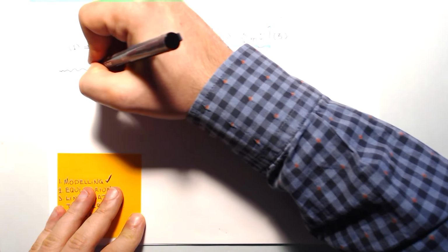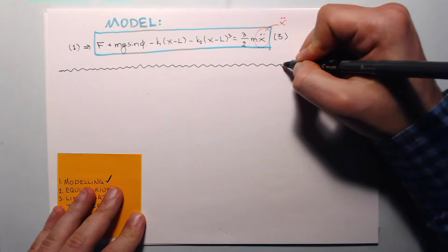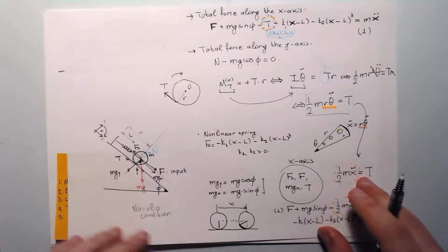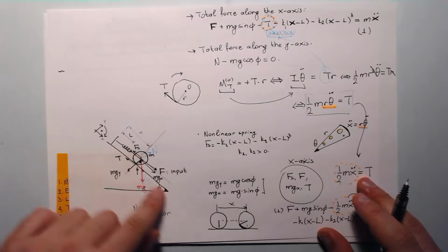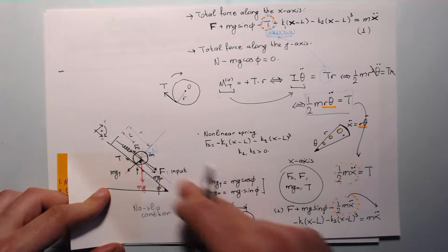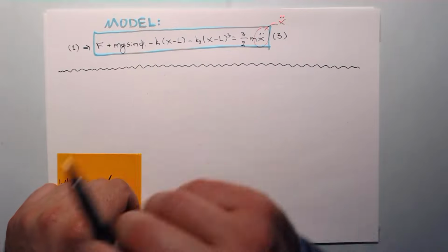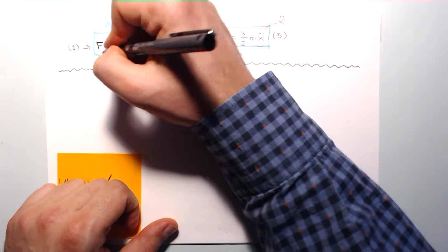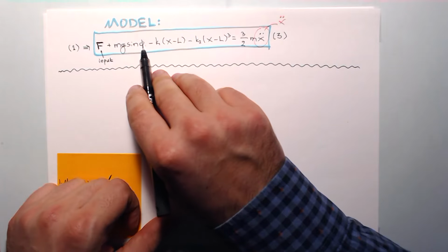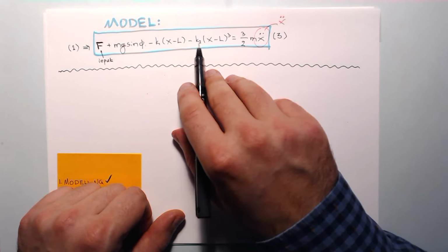Okay, so we derived the differential equation that describes the system dynamics, where recall here that x is the position of the ball on the inclined plane. We have derived a model that describes the horizontal position of the dynamical system. All the rest are f, which is an input. This is an input. M and g and phi are constants. K1 and L and K2 again are constants.